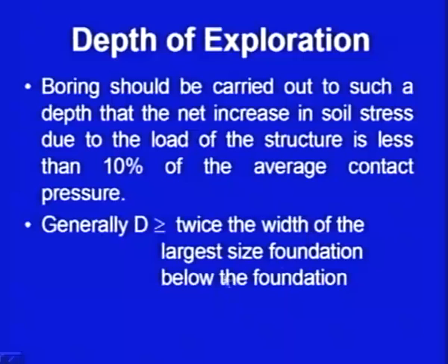So, we must go up to that depth, and roughly the depth of exploration is taken as twice the width of the largest size foundation below the foundation level. What it means is, if there is a structure and the width is, let us say, 5 meter, then you should take the exploration at least up to 2 times 5, that is 10 meter depth.